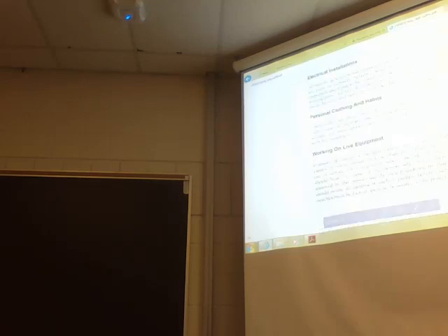Comfortable but close-fitting clothing should be worn. Wearing of insulated safety shoes is recommended when working on electrical equipment. Avoid wearing any loose articles such as rings and chains that may come in contact with live equipment. When working on live equipment, consider all circuits to be live unless one is certain that they are dead and cannot, by some human error, be made live.